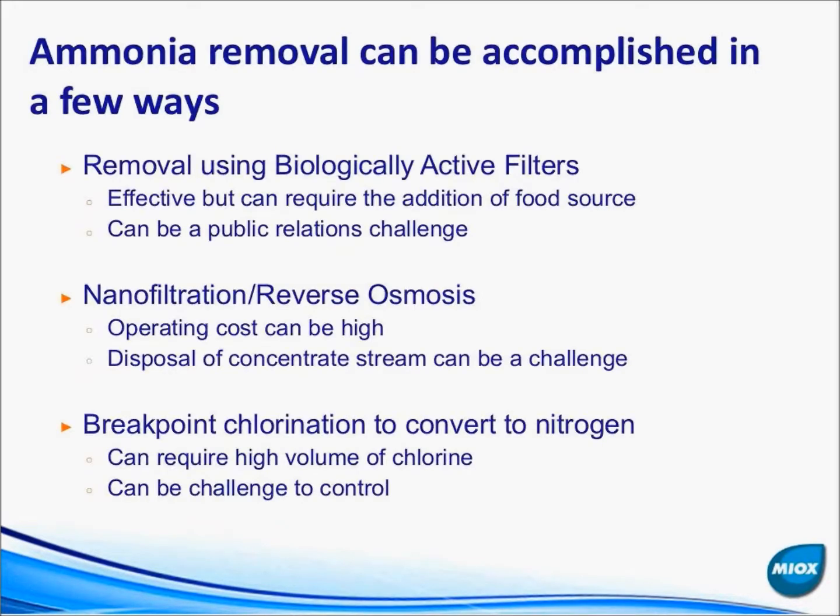So we'll move on to ammonia removal now, and as I mentioned, if you've sat in the other sessions, we have spoken about this a little bit previously, but it depends a little bit on where you're located. There are a lot of plants out there that struggle with ammonia in a surface water source. Typically, the bad actor in this case is fertilizer runoff, either from agricultural usage, or in some cases even from home use. So people putting fertilizer on their lawns, over-fertilizing, and having runoff out into the receiving streams.